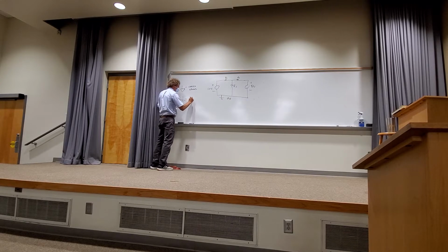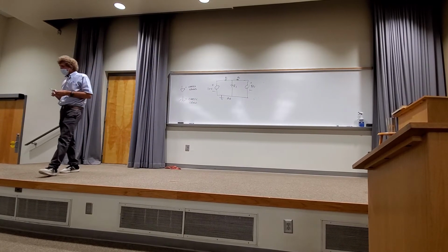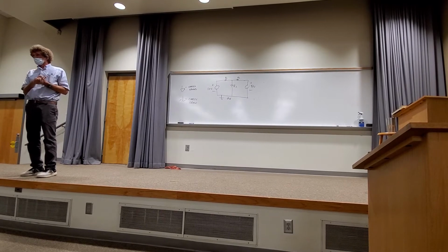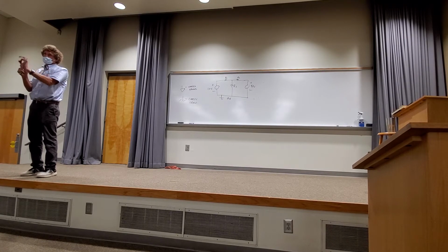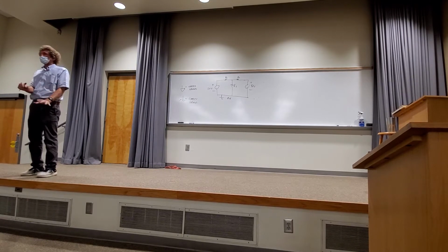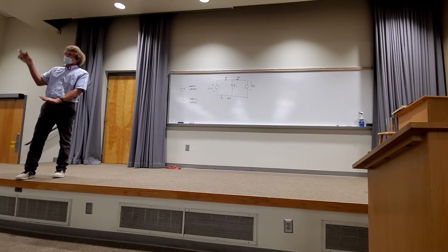That's a chassis ground. You don't have to worry about that. Earth ground is for if you ever are doing, actually the MEs might need this now that I think about it, something that involves buildings and things like that, you have to have an earth ground, which is a big fat rod of metal that you pound into the ground, and it is connected to the earth, and it will short out current to the earth itself. It's a safety feature for lightning protection and things like that. That's really an earth ground in a nutshell, without getting into the complexity.